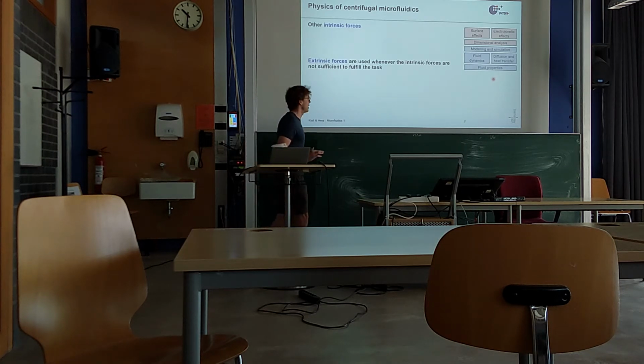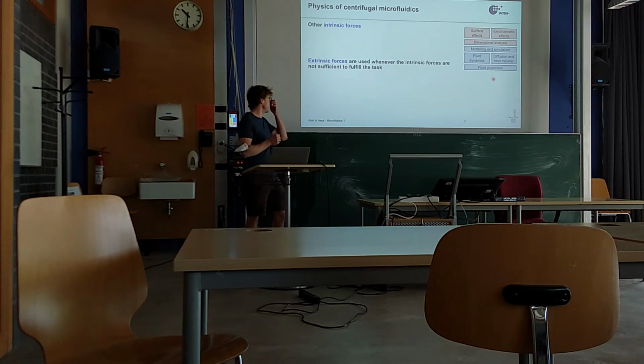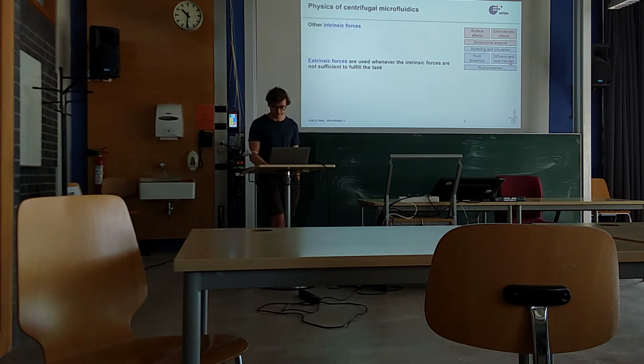So I think in the first lecture we presented an example where you compressed air and decompressed it again. And this is something that you can also use in centrifugal microfluidics. So you can compress air, store basically the energy inside the air, and when then changing the rotational frequency, this air will decompress and it can transport liquids. I will go into detail later on, but usually we call it pneumatic forces, which come from this air compression effect.